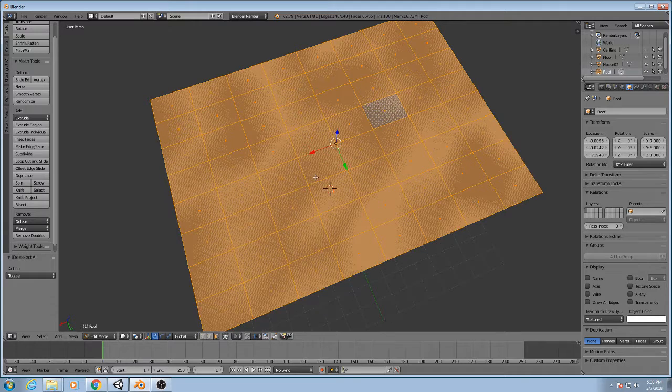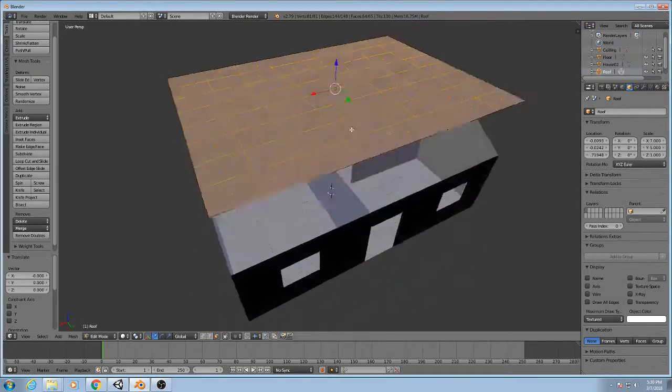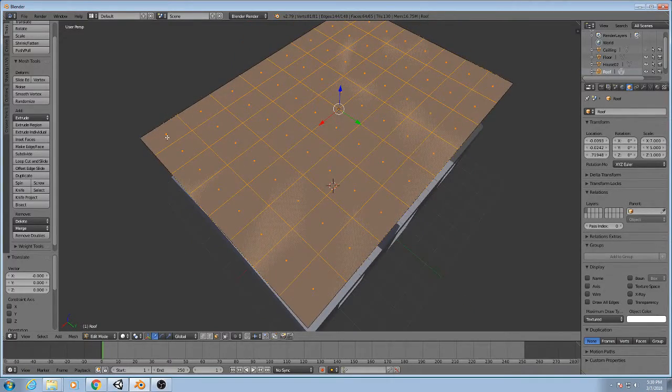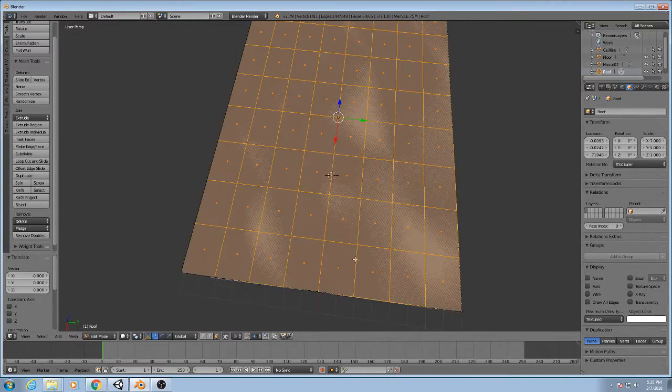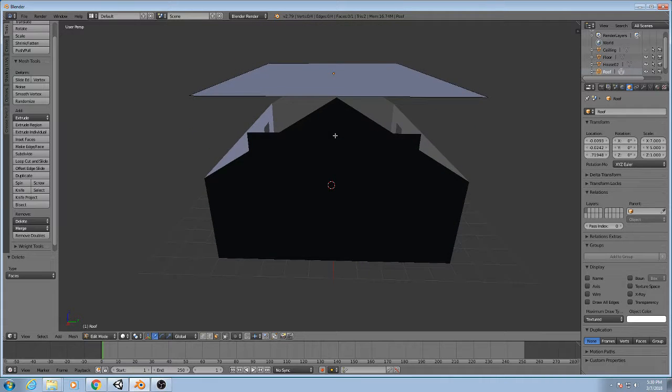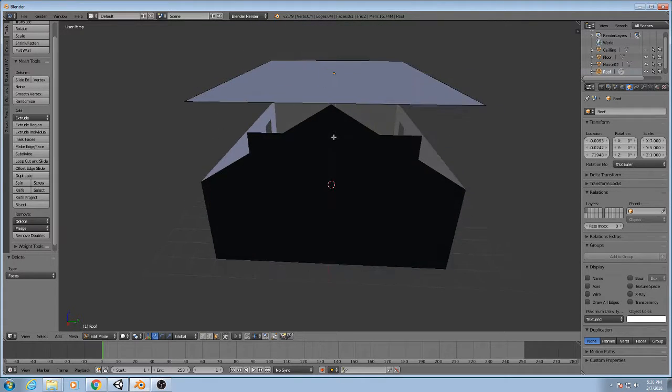We have to find the face by holding the shift button and clicking in the middle somewhere, by right clicking on it. Here we go. Selected the big face. That was just one single face, and all these other faces we're just gonna delete by pressing X, delete by face, and voila, we have just one face left.